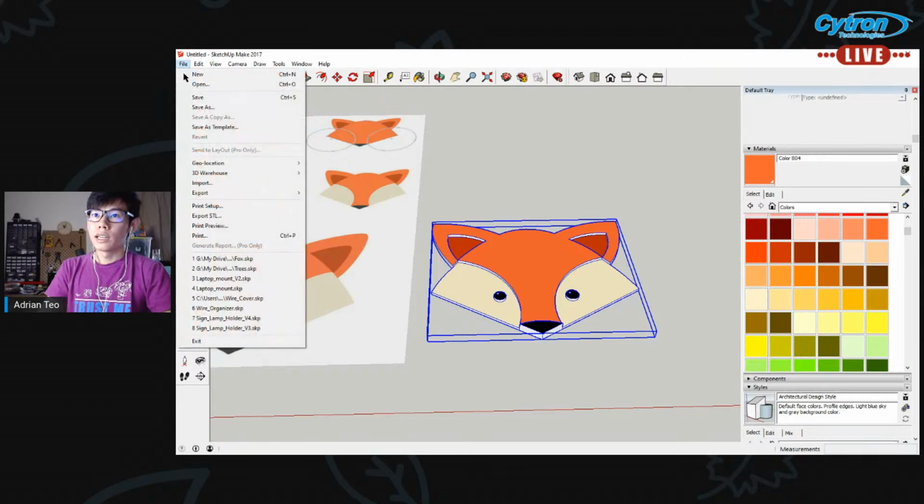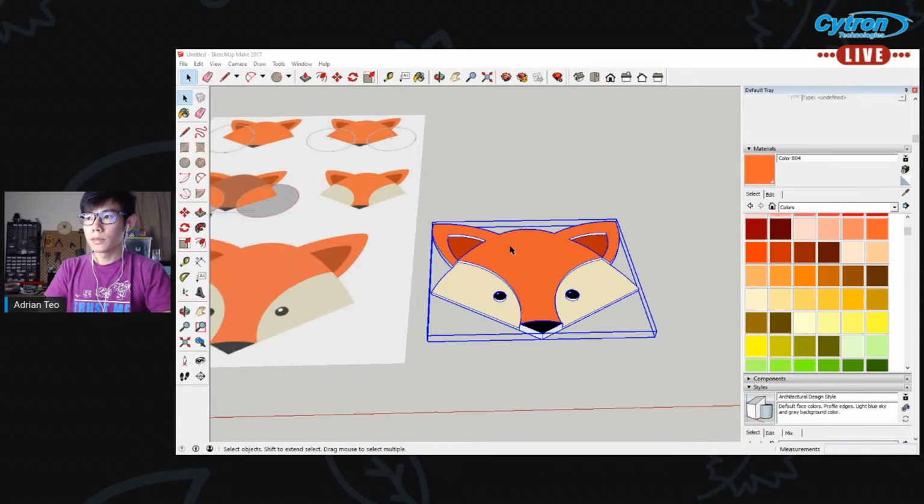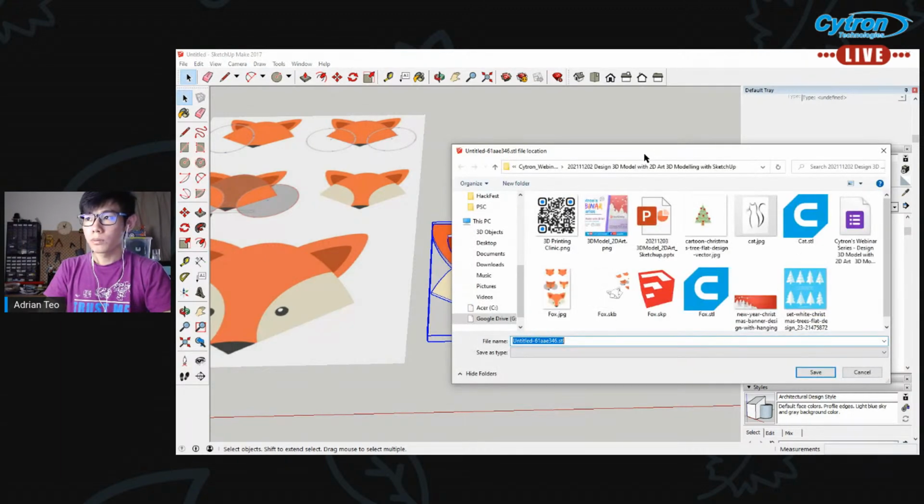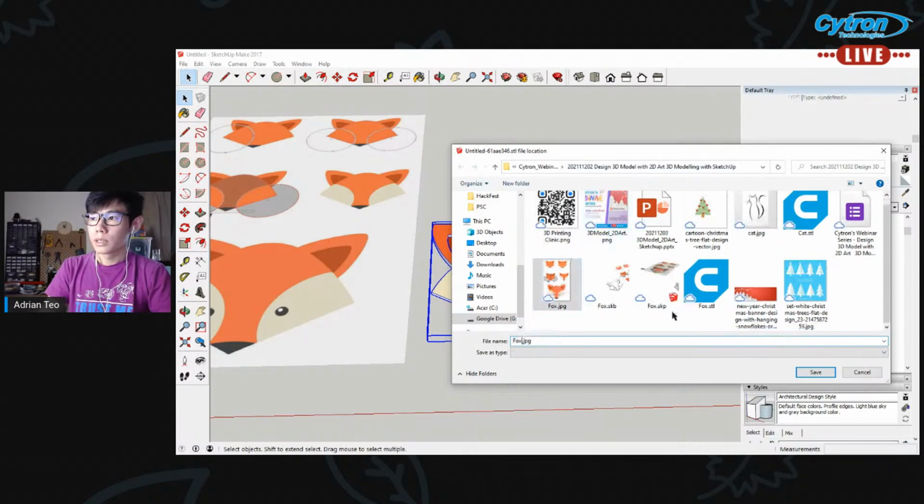So I'm going to go ahead, export the STL. Once you click Export STL, it's going to show you this. Select millimeters, binary, the file format, and then export the only current selection. Click Export and then select a location. Okay, Fox2. So it has to be .stl.